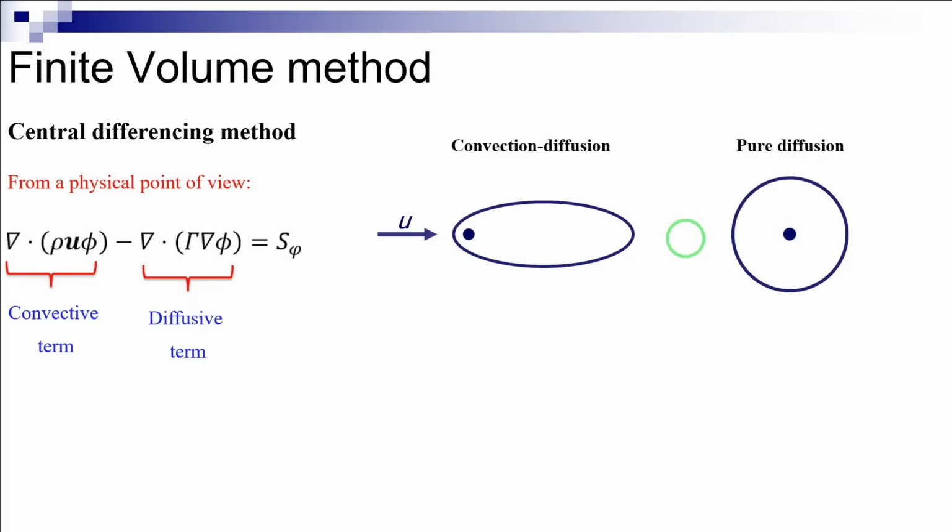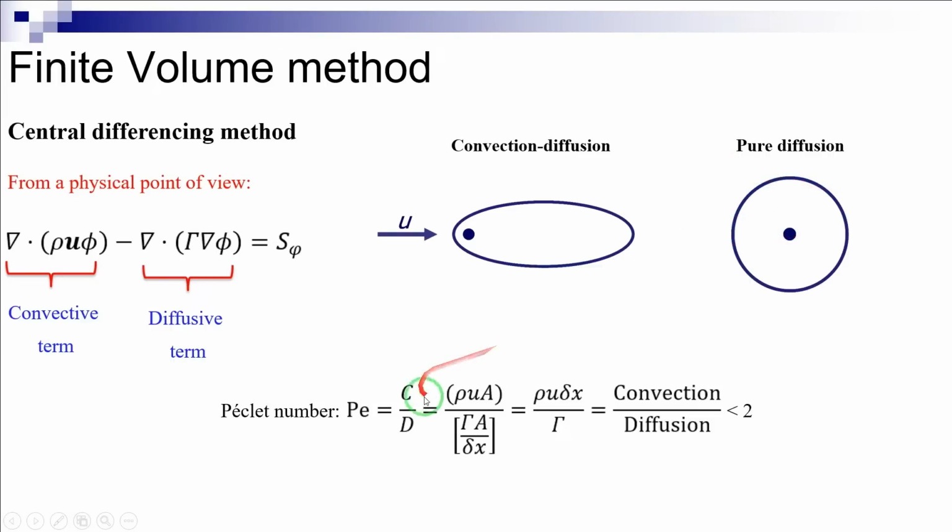The central differencing scheme is unable to account for the flow direction, and instead it considers that the fluid flow has the same effect on the upstream and downstream directions. Note that according to the definition of the Peclet number, this situation can be avoided by decreasing the grid size so that the Peclet number remains smaller than 2. For many practical situations, however, the increase in storage and computational requirements may be too large to afford. Moreover, for pure convective flows, this is simply not feasible. Therefore, a remedy is needed.